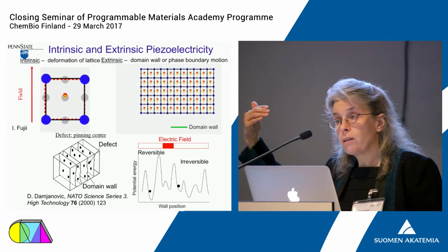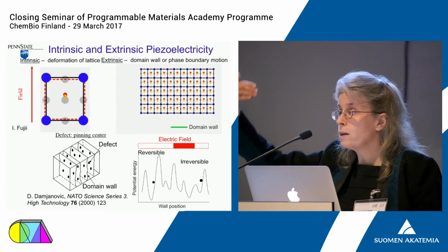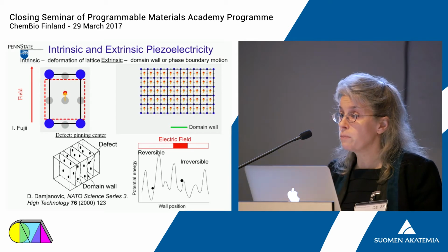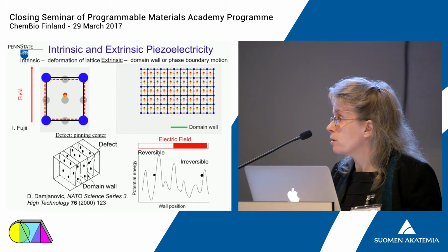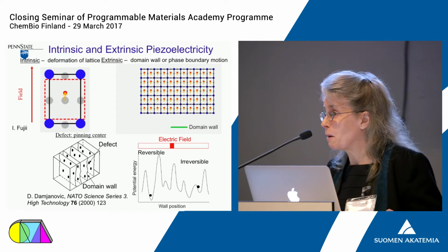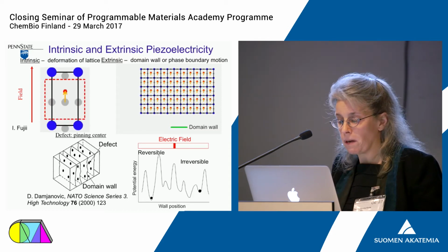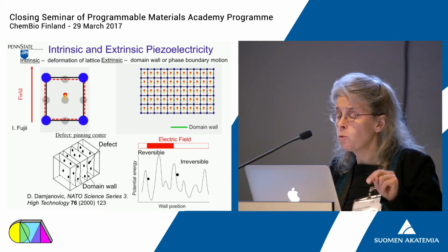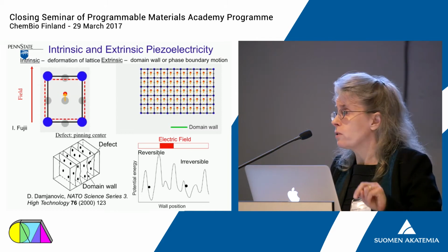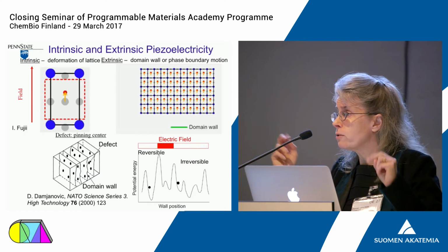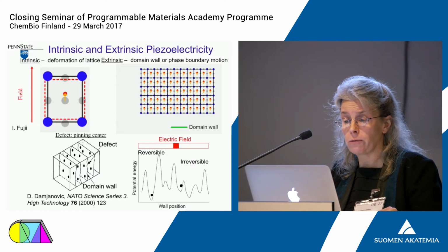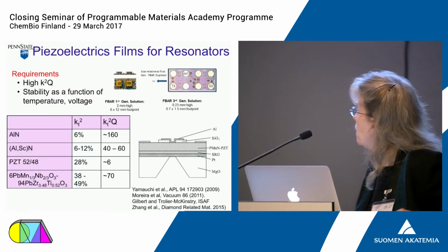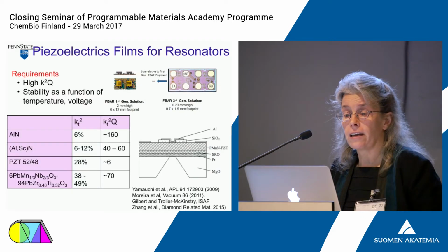But if I can actually move a domain wall from one potential well to the next potential well, the net result will be that I will develop irreversibility in the response. Larger responses, but irreversible responses. And we often will utilize choices between the relative magnitudes of the intrinsic and extrinsic responses to optimize materials for particular applications. So let me try and justify that here.